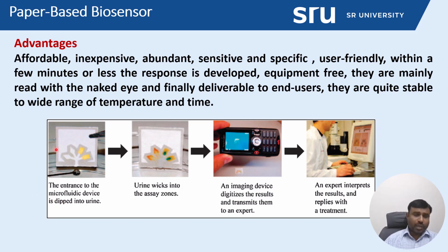Initially, the pattern can be created on the microfluidic device using a wax coating. This wax coating acts as a hydrophobic barrier, and the region without wax coating acts as a microfluidic absorber. So when you add some analyte, what will happen? It will diffuse and penetrate into all parts of the paper, whereas beyond that, the liquid or electrolyte cannot move because of the hydrophobic region from the wax coating. So this is the wax screen coating.